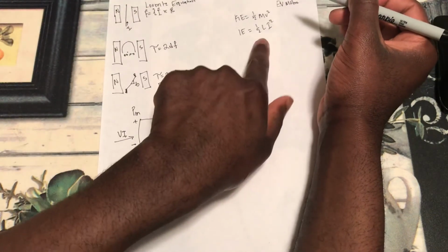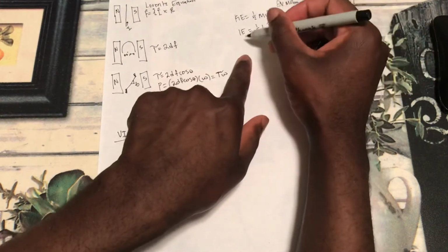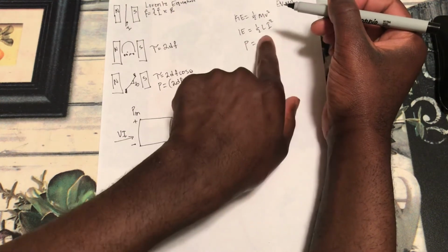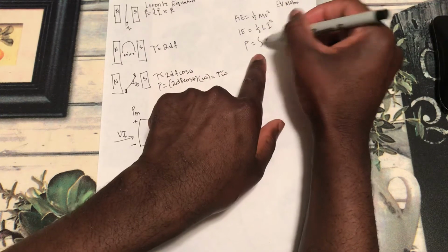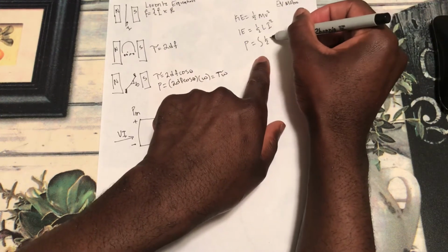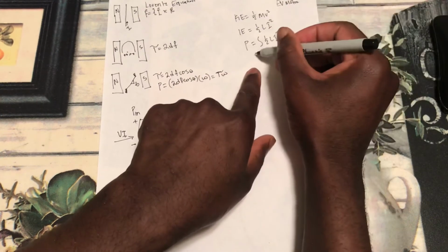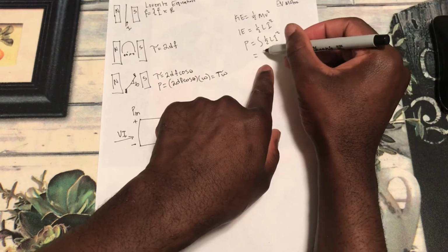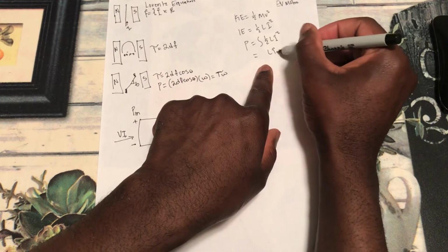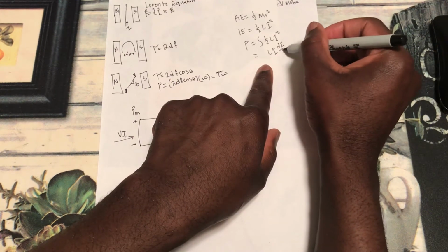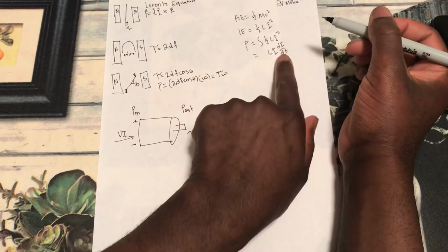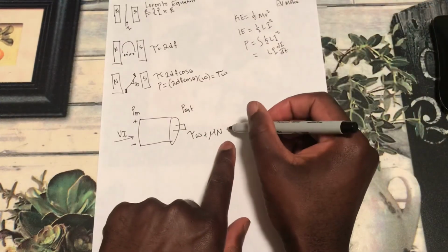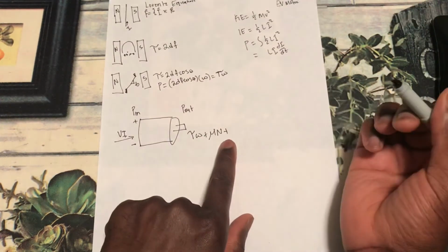From here, to get power we simply differentiate the inductance energy, and that gives us Li di/dt. So this is the power due to our inductance, and so now we bring that down here as well. That will come out of our motor.